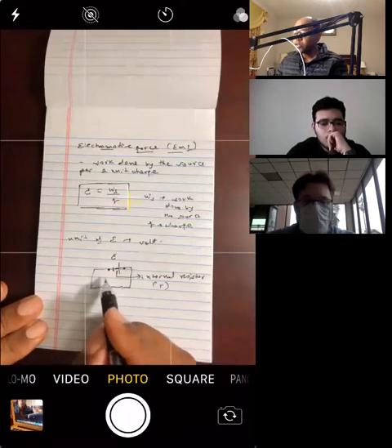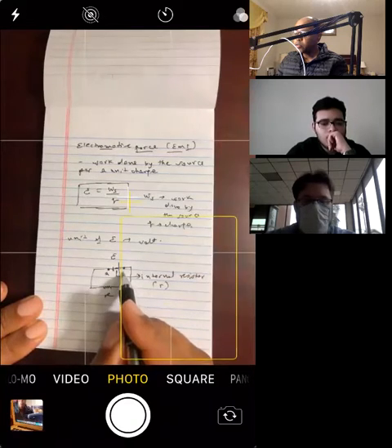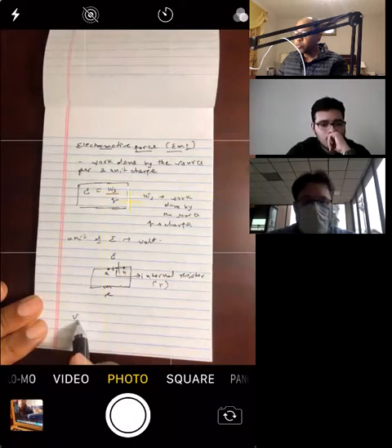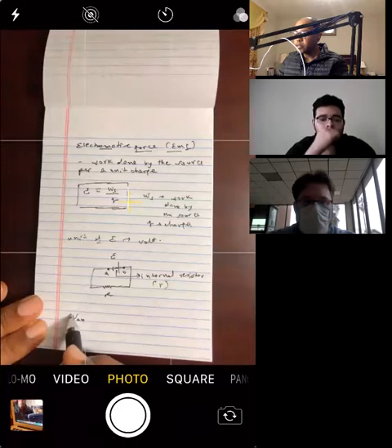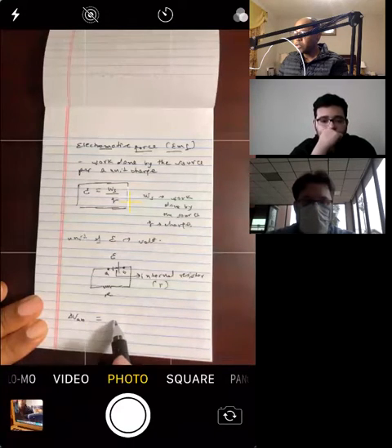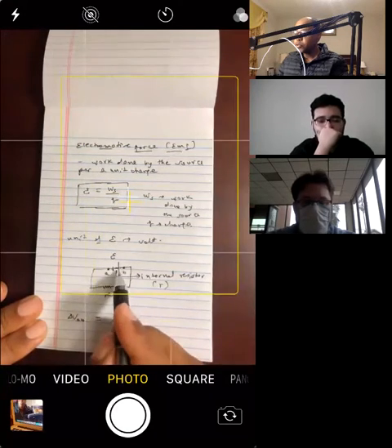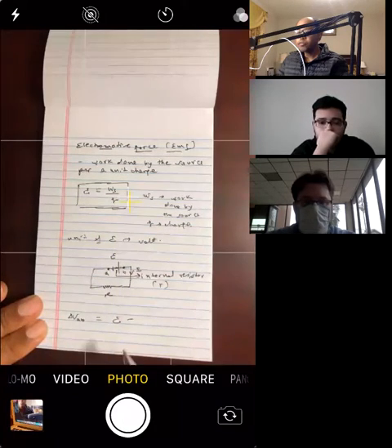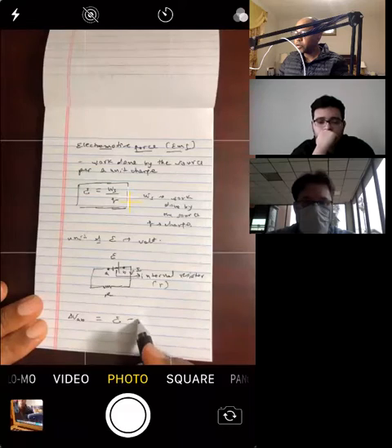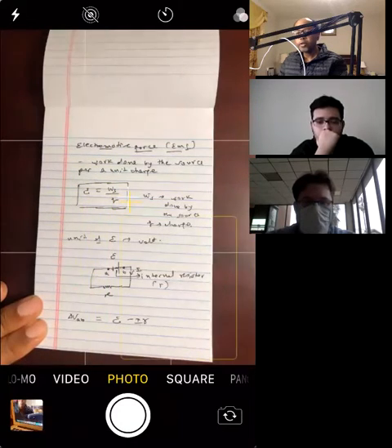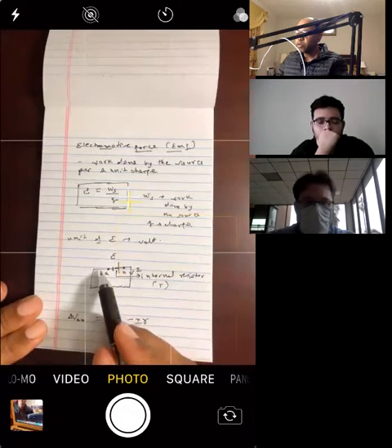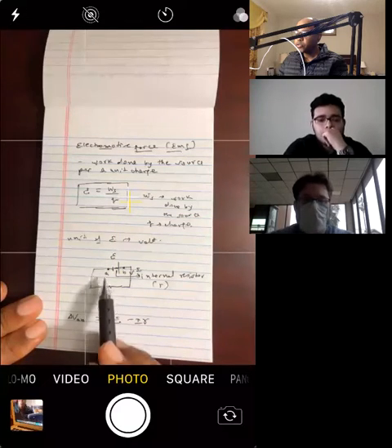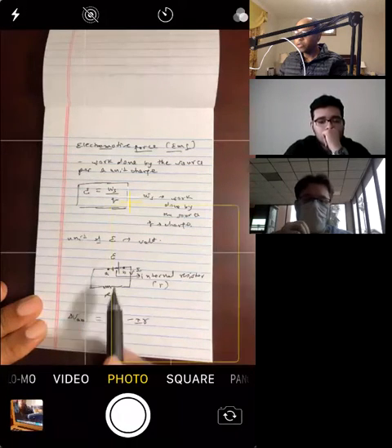Okay, so let's say this is point A, and this is point B. The potential difference between points A and B, delta V between A and B, is the EMF minus the potential drop in the internal resistance. Suppose you have a current over here, and that potential difference is current times resistance. So the potential difference available to the external resistance is delta VAB, not the entire EMF.